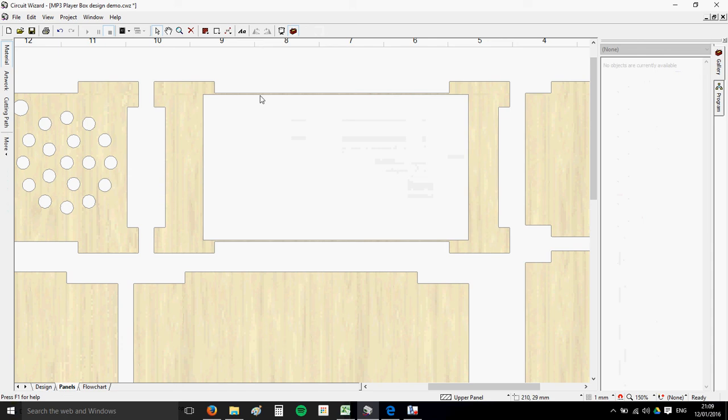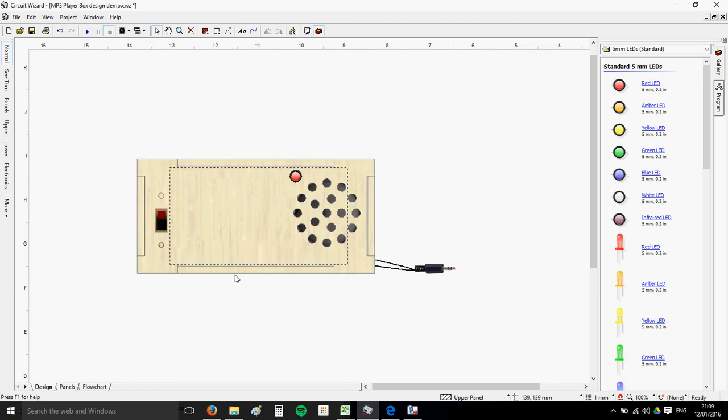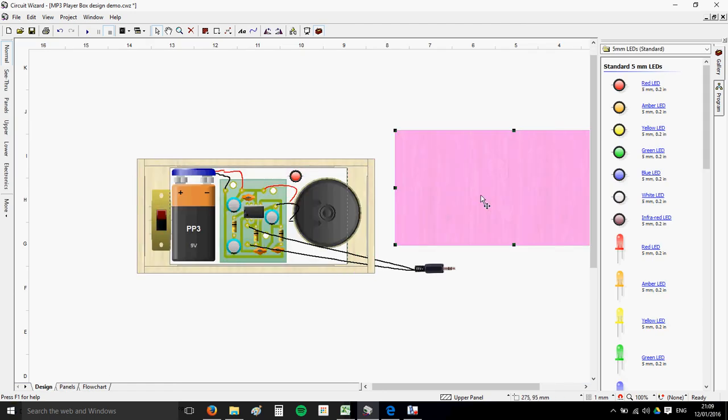Right. Hopefully you will notice an incredibly thin piece of wood between that hole I made and the little notch I cut out. That is obviously not going to work if we put it in the laser cutter. If you put that in the laser cutter, the laser will just vaporize that little bit. There'll be nothing left. So we need to rethink our design. We could either make the hole smaller or we could make the whole box bigger. So this is where it's nice and easy and a bit friendlier than Inventor to change.